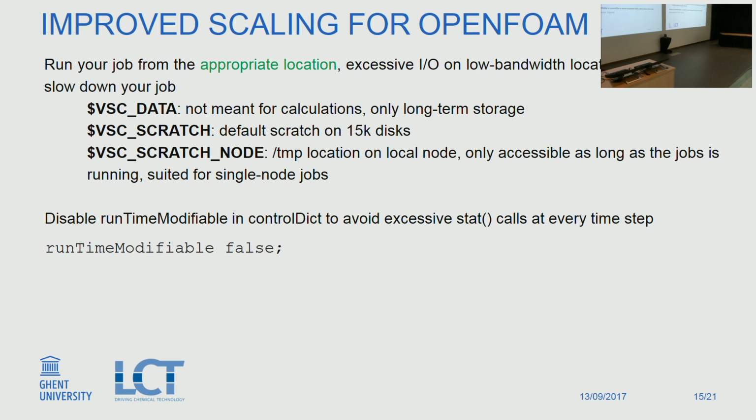One thing that I saw when researching for this presentation is the statement runTimeModifiable. It's something that's in controlDict, and it allows you to change the files at runtime. Every time, OpenFOAM checks at the beginning of a new time step whether the files in system and in constant have changed. And if so, it will apply the changes in the next time steps.